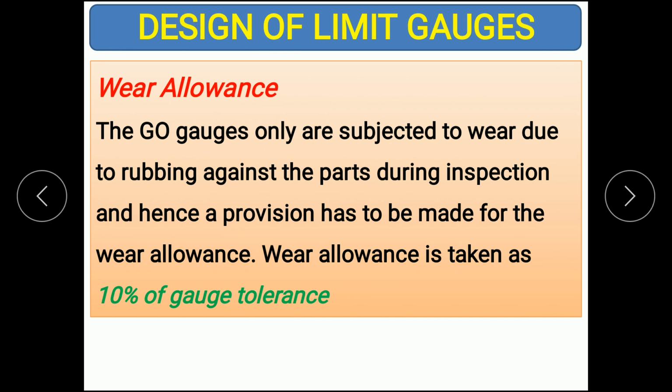We shall see these details while solving the problems on gauge designs. Wear allowance is taken as 10% of the gauge tolerance. Whatever we have seen as the introduction to design of limit gauges, we shall see again in detail while solving the problems on gauge design.